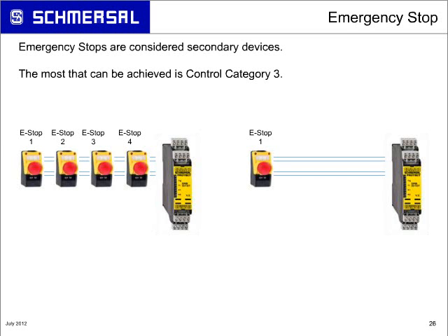With an E-stop, it's very rare that you can even come close to achieving a control category 4 emergency stop. For one thing, an emergency stop is not a primary safety device, it's secondary. It's also mechanical. It has to be hit, and it's tripping a mechanical mechanism to trip those redundant contacts that are mounted to it. So you do not eliminate the possibility of mechanical failure within an E-stop.